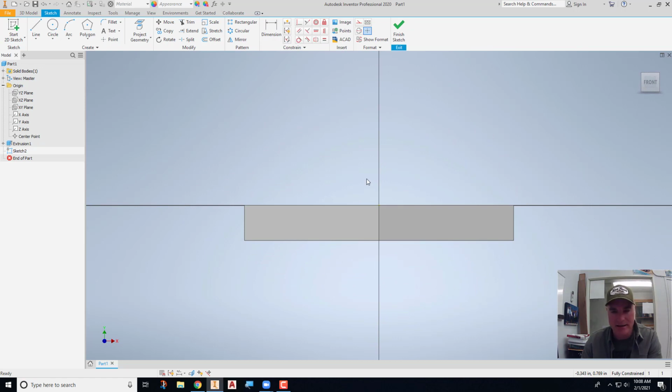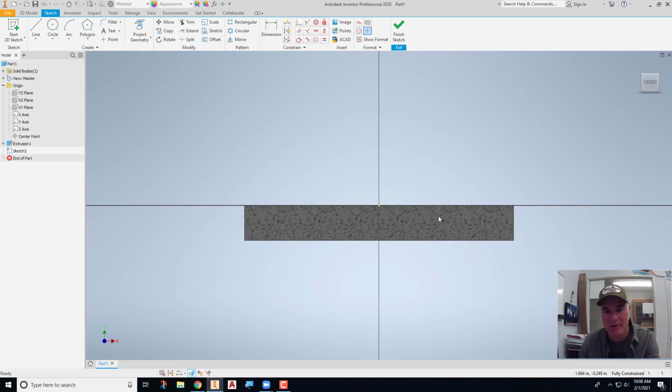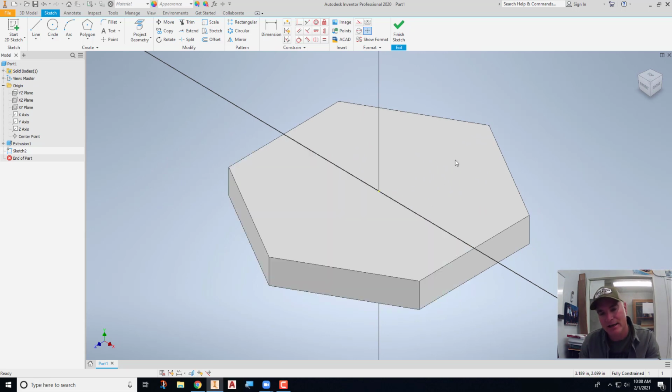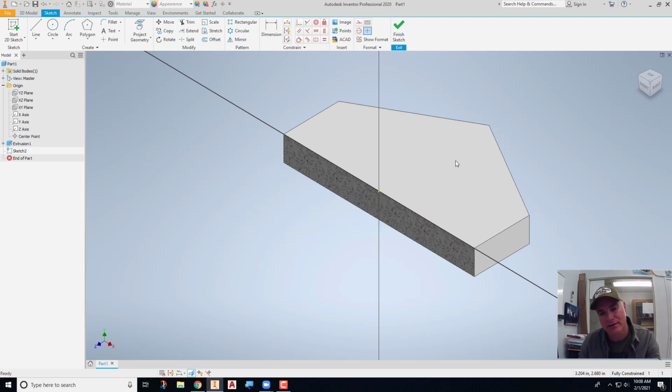In order to see that sketch plane, you'll use the slice geometry command, which is F7. So notice I press F7 and it now kind of gives me a cross section, if you will. If I rotate it up so that it's an isometric view, I've actually cut through the object. I press F7, it turns it off. So F7 does that slice geometry. And now what I can do is I can come in here and draw the geometry that I want.